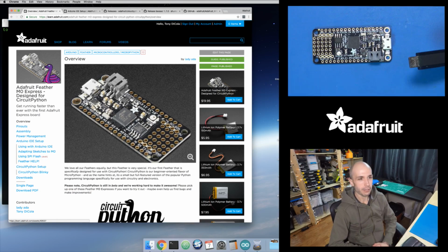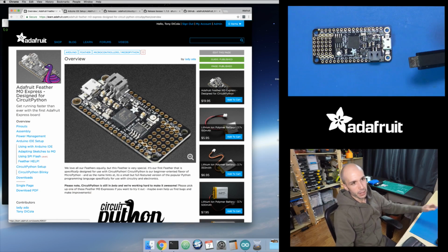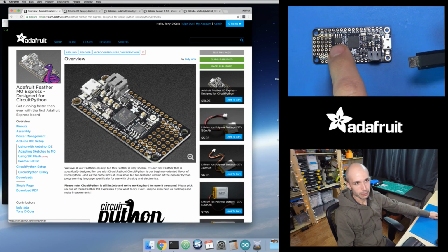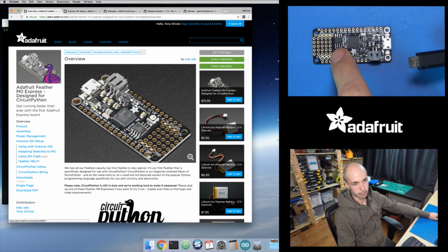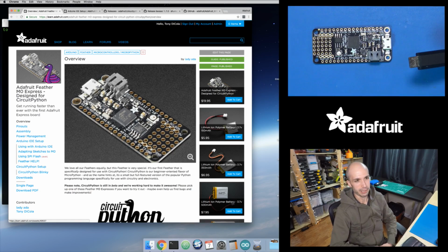And that's really cool because with CircuitPython, what we can do is say all of your Python scripts and code lives on that 2 megabyte flash chip, and then all of the CircuitPython firmware lives on the 256 kilobytes of microprocessor flash space. So that gives more space for CircuitPython code. The firmware can add more features and more functionality into it. And then it gives you more space for your Python scripts, a lot more space. So with 2 megabytes, you can store quite a large program on there, but what you'll end up really storing, I bet, are probably a lot of libraries and data files, external things on there.